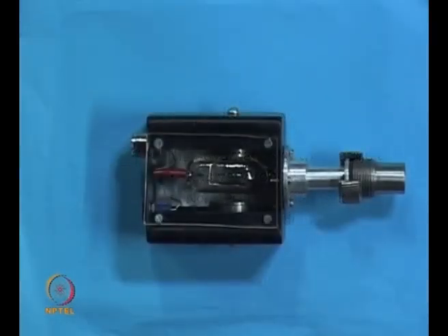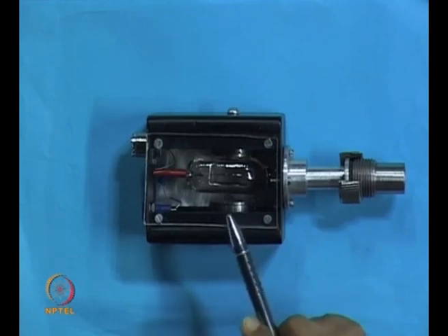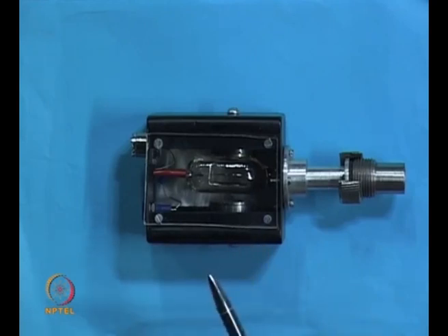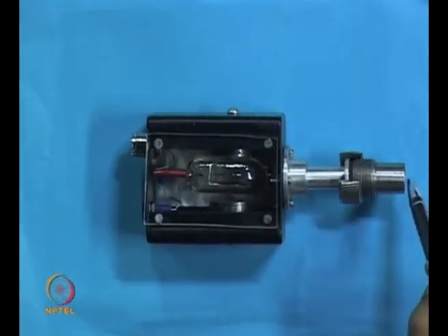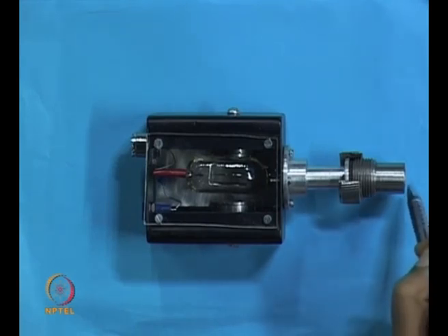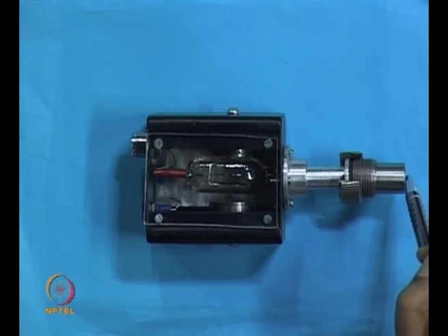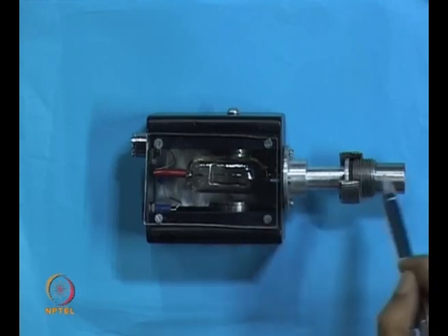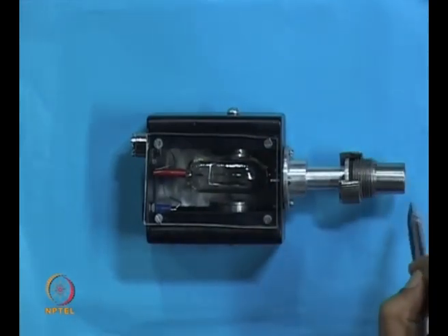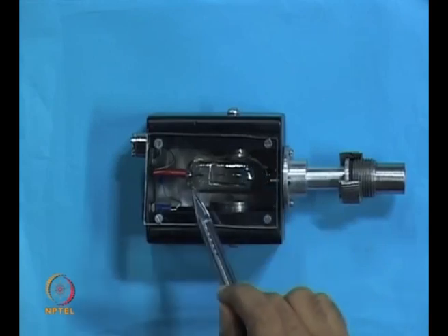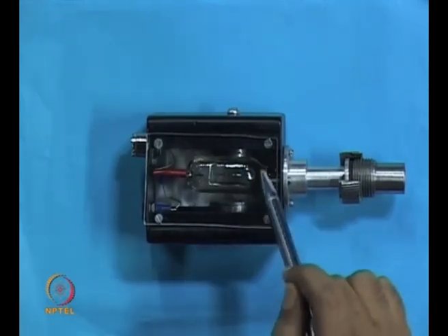So after understanding how the cold cathode ionization gauge works, or how a Penning gauge works, I just want to show you how it works basically, and whatever we have just learnt, you can see in an actual case. So this is how a Penning gauge looks, and this portion I would connect in a line of which I want to measure the pressure. If I want to measure the pressure up to -6 millibar, -7 millibar, this element, the head of the vacuum gauge, is going to be connected over there, and this will be sensed in what we have, an arrangement for cathode and anode here.